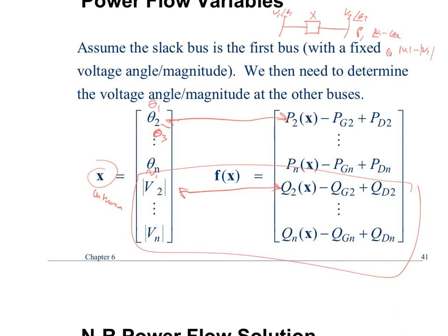So again, if you're really comfortable looking at load flow, you can just look at results, at bus magnitudes and angles, and you can tell that it seems really wonky that the voltage difference here is that high, because the reactive power doesn't seem like it should be that high. People that have been doing it for a few years can just look at quantities and make an assumption saying this is right or this is wrong just by looking at magnitudes and angles. Okay?